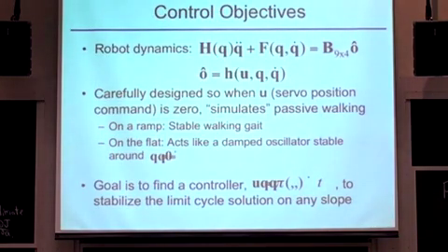Got the robot dynamics. Oops, I've used a Mac now. I used to use Windows, so apparently my u is now an o hat. Sorry, that's actually tau. Okay, so tau. I had almost the manipulator equations, but I had to go through this little hobby servo, so it wasn't quite the manipulator equation. The goal was to find a control policy pi that was already stable down a small ramp.